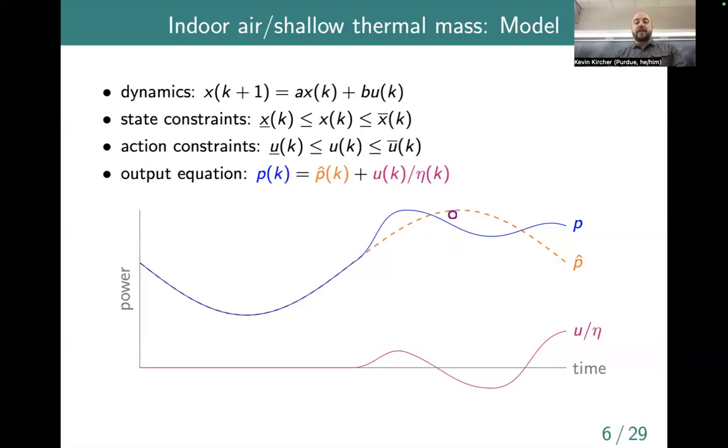So again, if this is air conditioning, this is about 4 p.m. The overall grid might be panicking if this is a super hot day. They might be running out of capacity, it might be at risk of power outage, something like that. So in order to alleviate strain on the grid, we want to basically shed some load during that period, reduce our power consumption. But if we just do that without doing anything preemptive, then we just let the building get really hot, and so people might get kind of annoyed. So this is what you might call a load shifting profile.